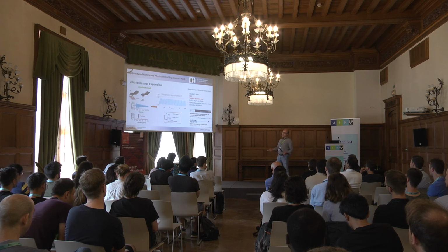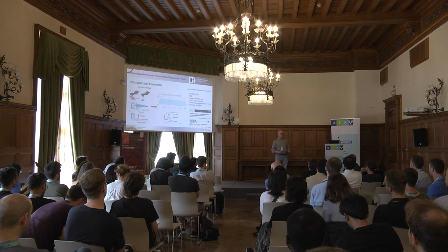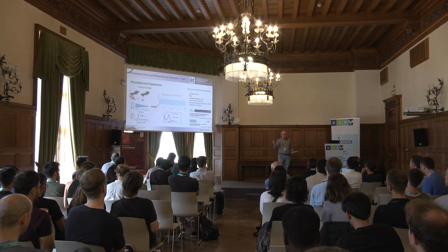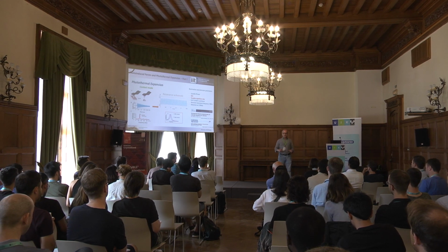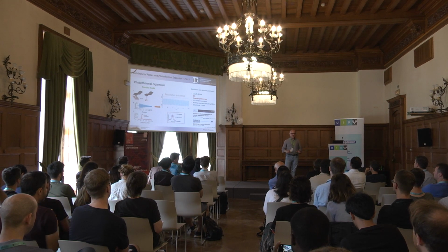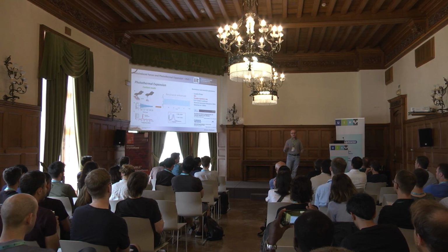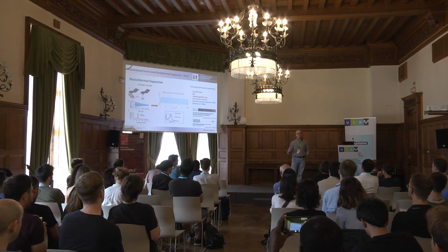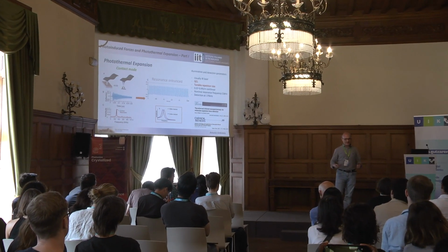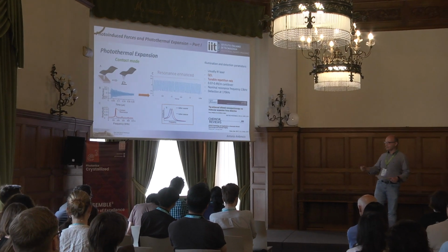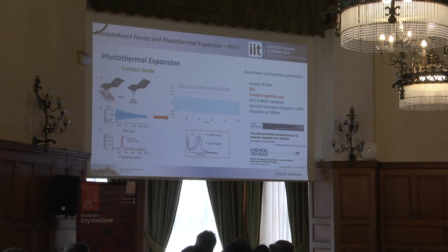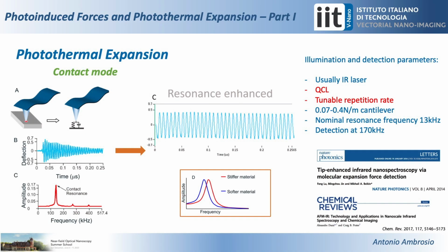So again, there is the frequency shift to the material, and this would be very sensitive to any frequency shift. So you have actually to use a PLL to look at the frequency shift. Otherwise, you convolute your material information with whatever absorbance is, and you have a mixed-up kind of signal, where your signal will be modulated by the frequency shift instead of the local absorbance. So this is very important.